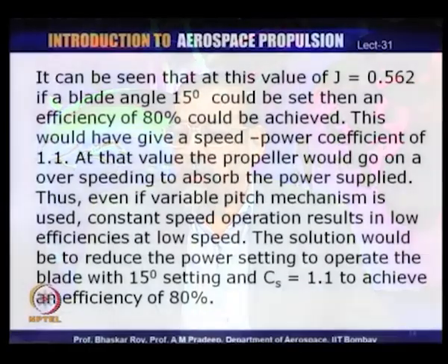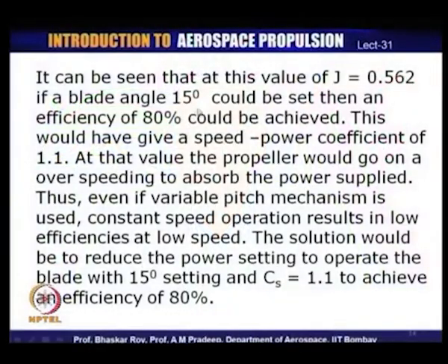What can be done is, if you now set the blade setting at 15 degrees, you could actually get an efficiency of 80%. This is possible with this propeller, and the blade setting angle could be used to get a higher efficiency. This would have given a speed power coefficient of 1.1. At that value the propeller would overspeed to absorb the power supplied.